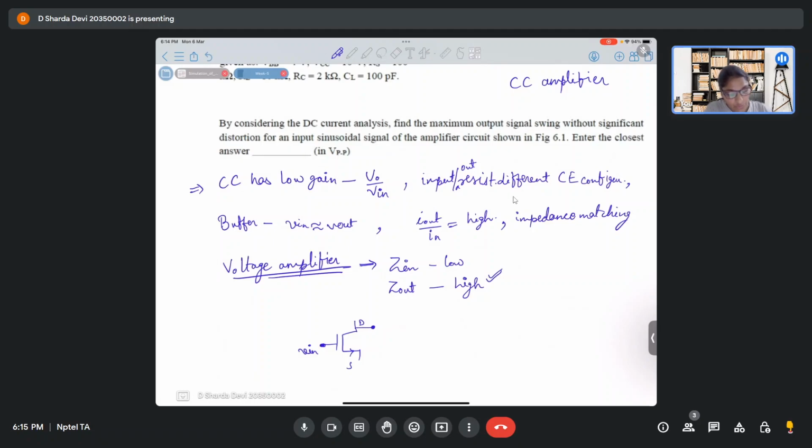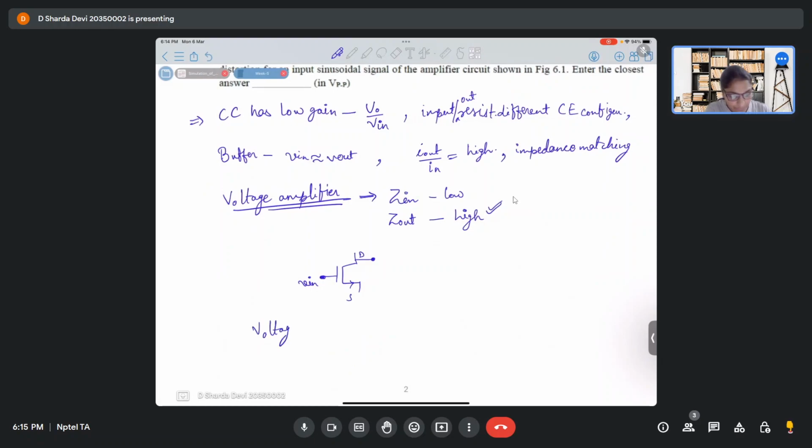First of all, voltage amplifier मतलब क्या होता है? Voltage amplifier means voltage to voltage conversion, right? Yes, ma'am. So if I want my output voltage to completely drop across my load, so let's say this is R0, which is the output impedance, or Z out, versus RL. I want my V out to drop across RL. So what will be the value for RL?